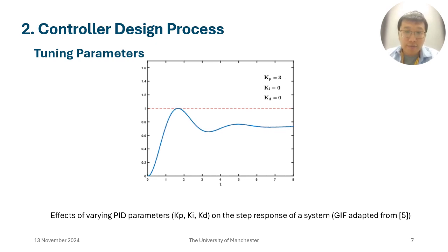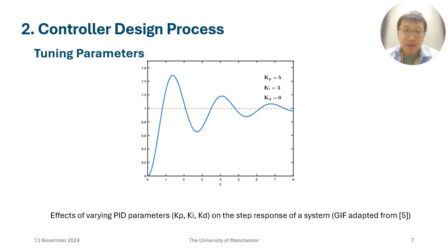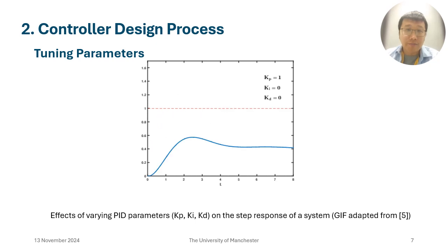So we can look at it again. The proportional term, then the integral term to remove the steady state error, but there are oscillations. Then we use the derivative component to smooth that. That's the overshoot we're reducing now.